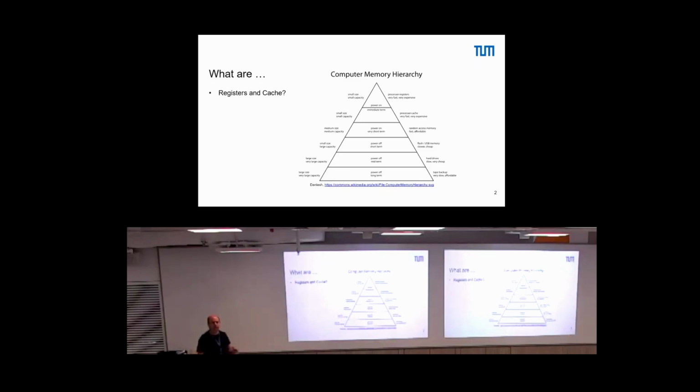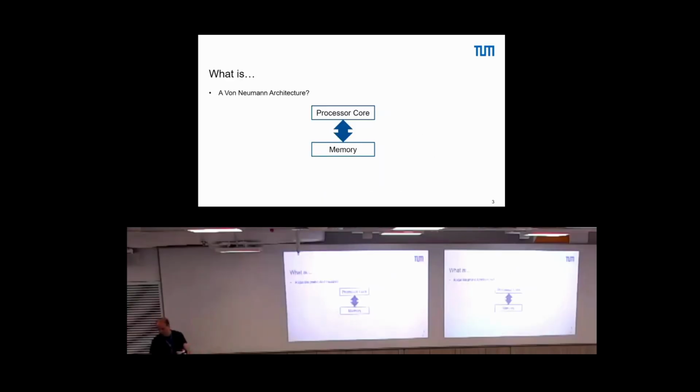So the difference is we have here for von Neumann one memory for the processor core, and this memory here has data and instructions. That means if you want to load over a fixed width bus, you do not want to have this arbitrarily large. If you want to load data and instructions, then you would usually first fetch the instruction, then fetch the data.